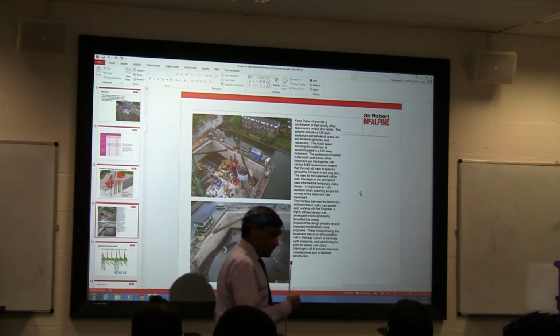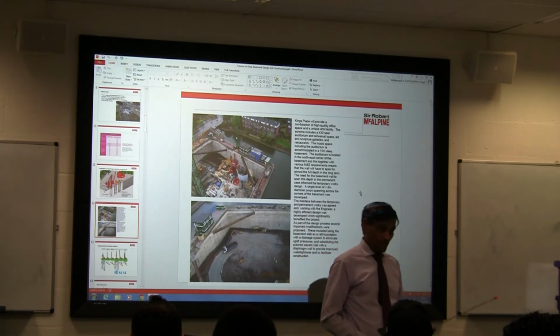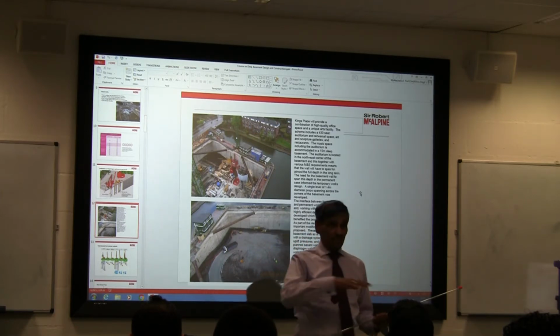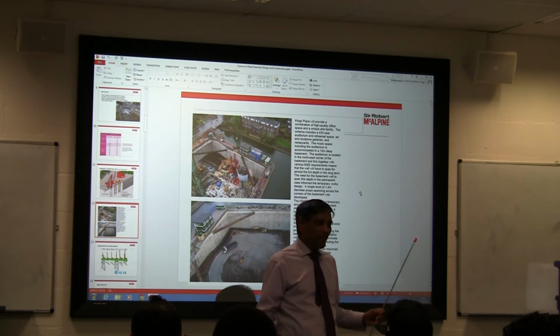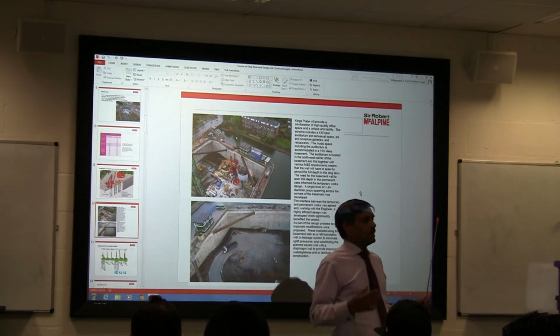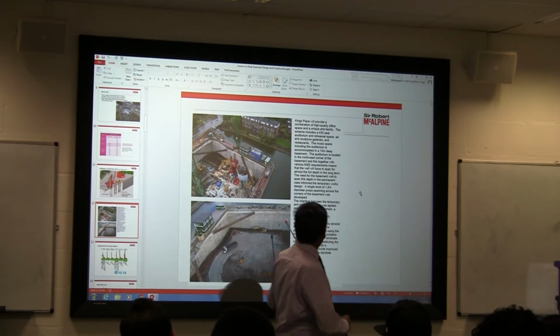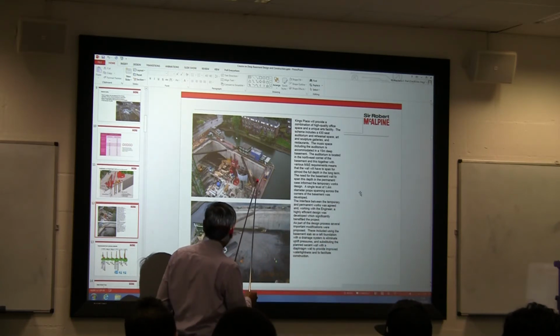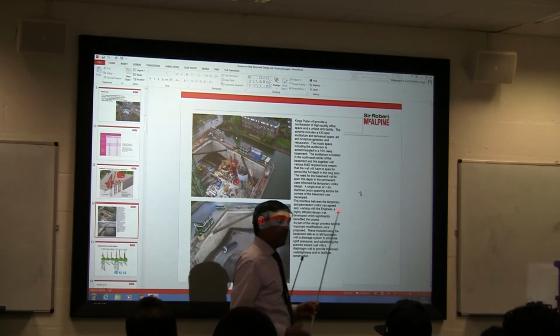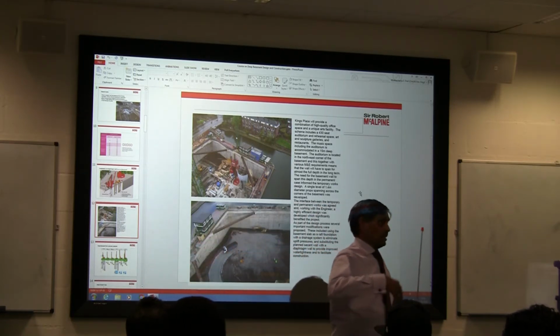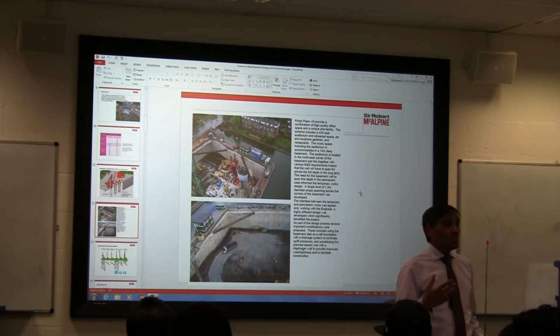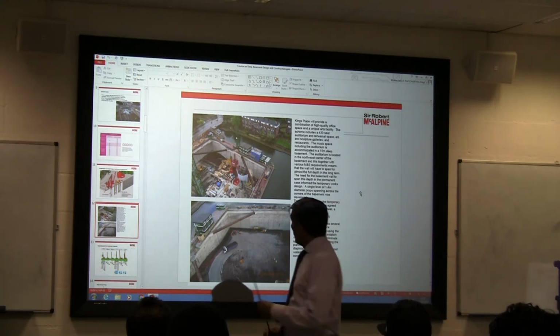But you will see soon, it's very, very expensive. And it sanitizes the site because you need a bentonite plant. If you're talking about a pile, concrete, or let us say in that panel, the concrete that goes in there, remember it goes another 4 or 5 meters below the excavation also. We're talking about, let us say, 300 cubic meters of concrete. That means you need 3 times more bentonite, so 1,000 cubic meters of bentonite I need on site.